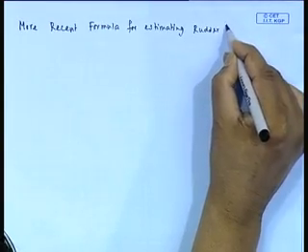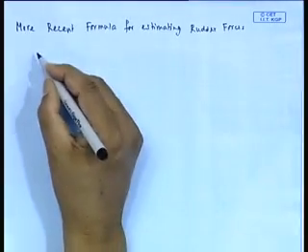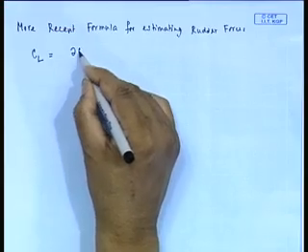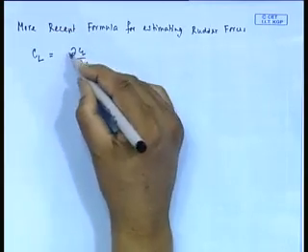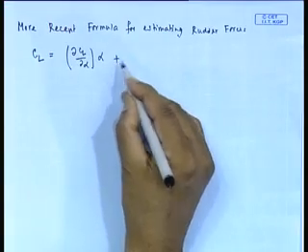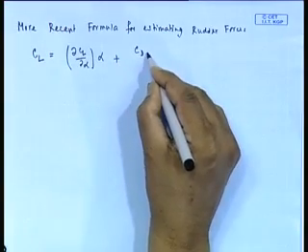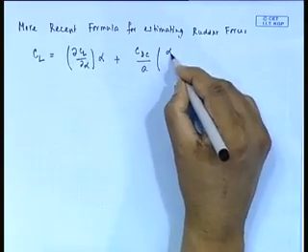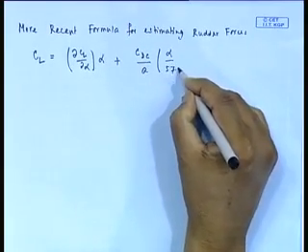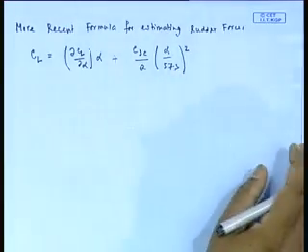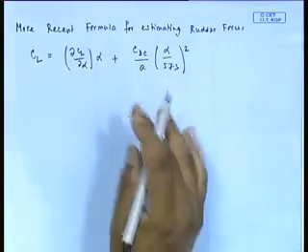Let me preamble this as the more recent formula for estimating rudder forces, so that we know that here it says CL, it is dCL. Now, there is another problem that will come. Of course everybody knows it will be this, but the essential thing is the correction term, dCL by dα, times α by 57.3. The α is the angle of attack in degrees, that is why it is divided by 57.3.